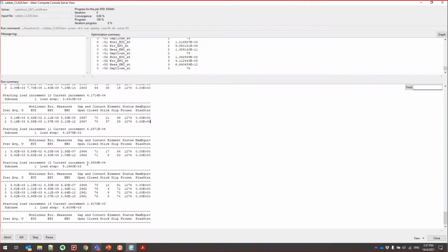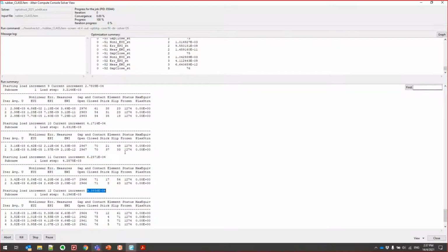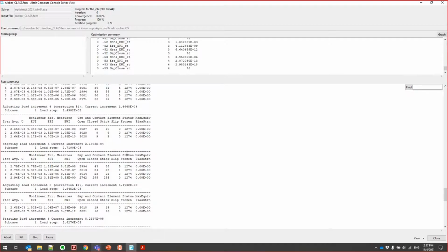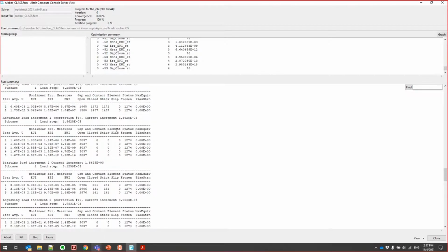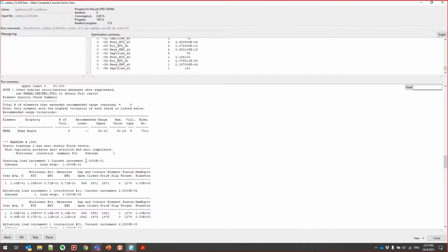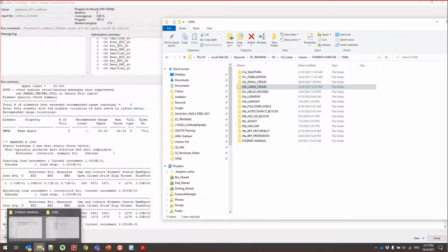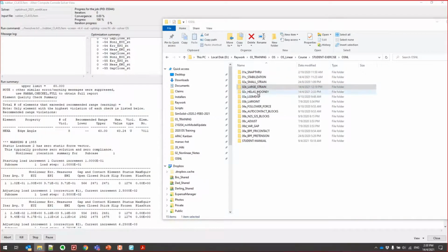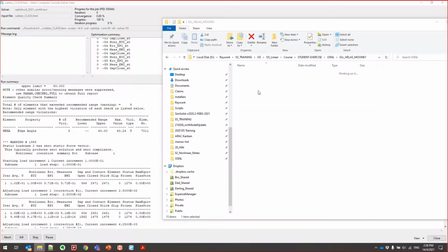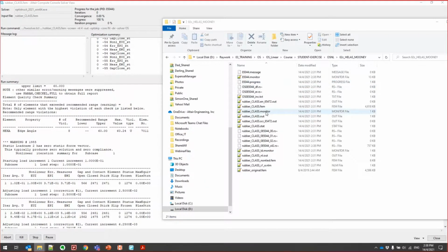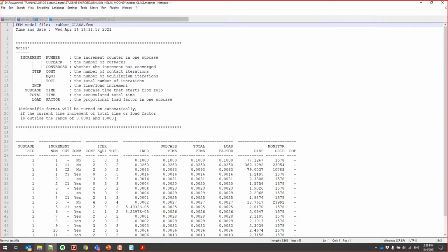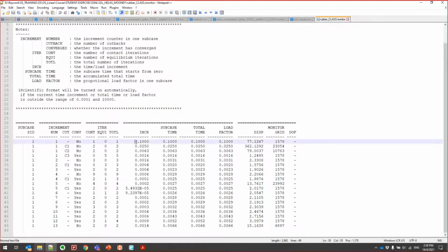It's slow now. The increments are actually very small, or maybe because I started with a very large time step. The initial time step will have an effect, as it will determine whether you get convergence very early on or not. Let's look at the monitor file. You can see that the first time step of 0.1 is actually too large. So non-convergence, it cuts back, and cuts back smaller, and cuts back smaller.